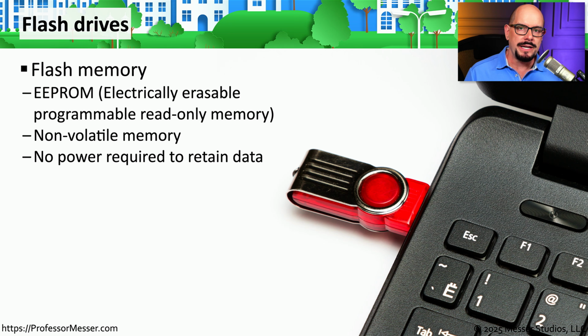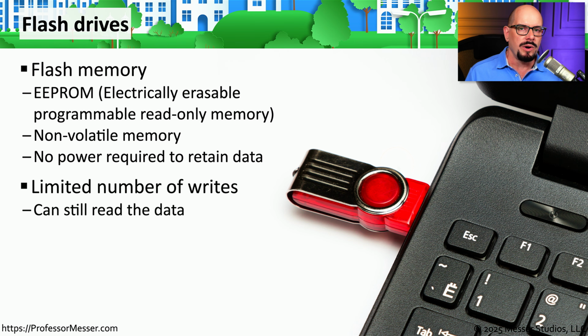Flash drives are a very handy way to store information into a very small form factor. They consist of EEPROM memory, that's electrically erasable, programmable read-only memory. This memory is non-volatile, so you can remove it from your system and the power source, and all of the information stored on that flash drive will continue to be available. EEPROM is a technology that allows a certain number of writes, but at a certain point, it will stop writing that information to the drive. You may still be able to read the information from that drive, but you won't be able to write anything new to that drive going forward.